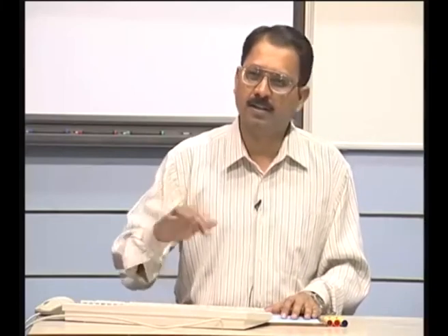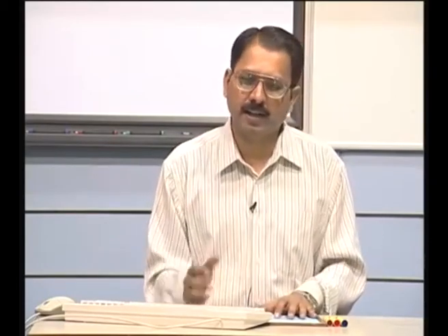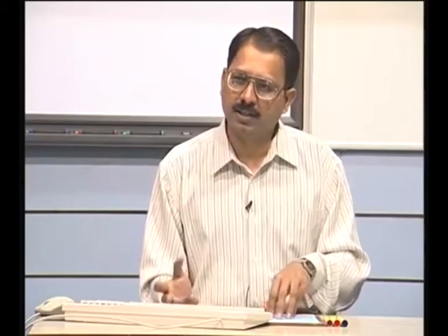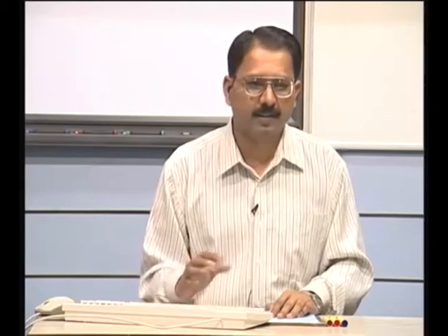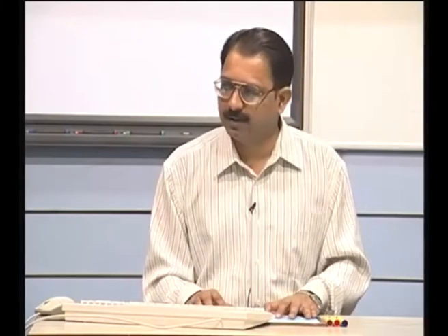So, one can say that the study of geometric modeling constitutes 2 different major branches. One is the study of curves and surfaces, what we did so far, and another is the study of solids using solid modeling techniques like boundary representation, constructive solid geometry, or spatial enumeration techniques. So, that would be the subject for our next class.